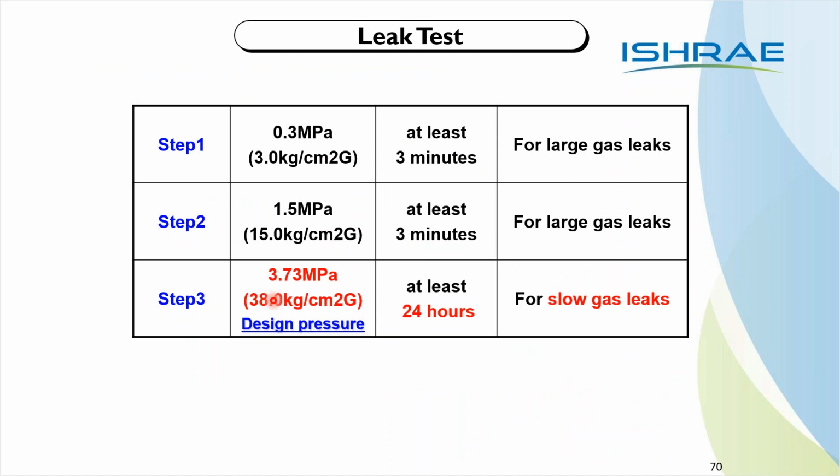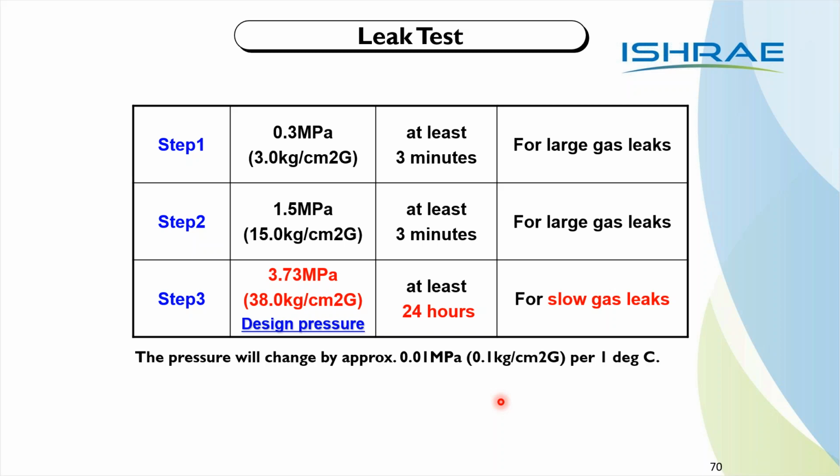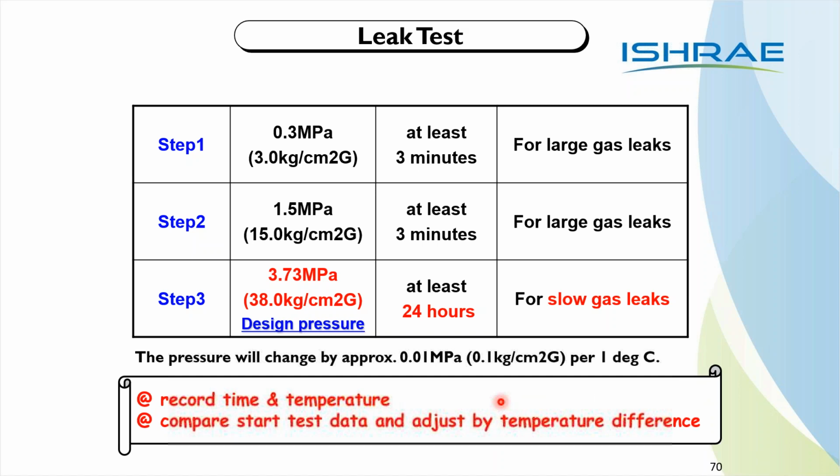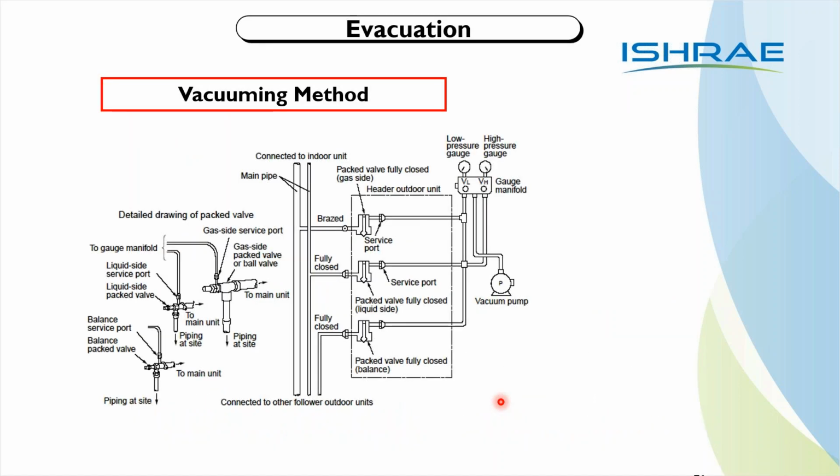Then again, this I have explained to you earlier also, minimum 450 psi, or you can go up to even 500, 550 psi on the high side. On the low side, limit yourself to 250 or 300 or 400 psi, not beyond that. Then the pressure will change based on your ambient temperature, which we have explained earlier also.